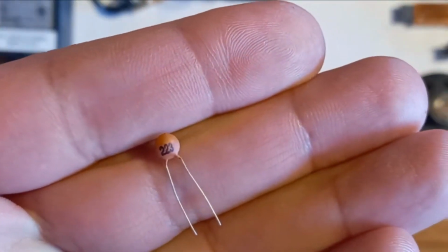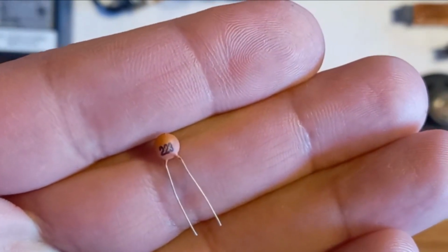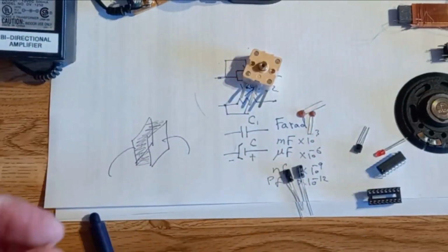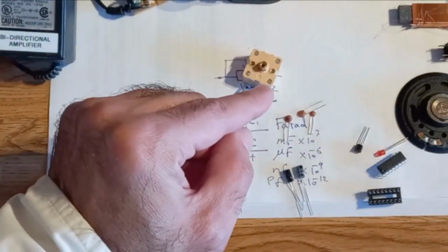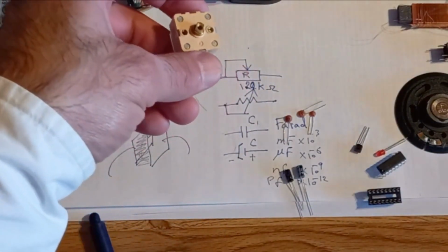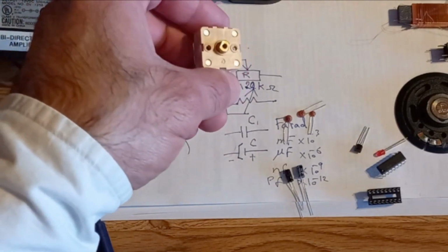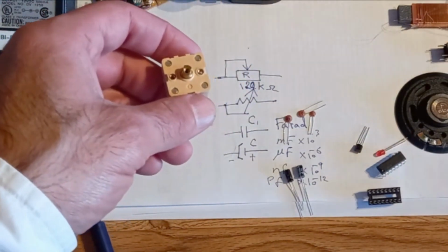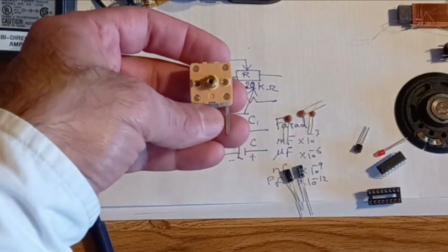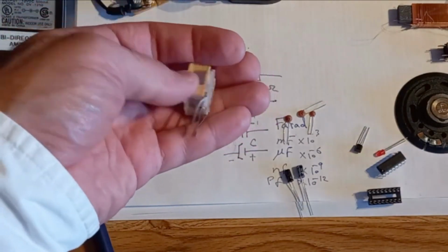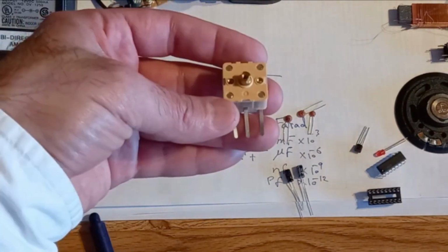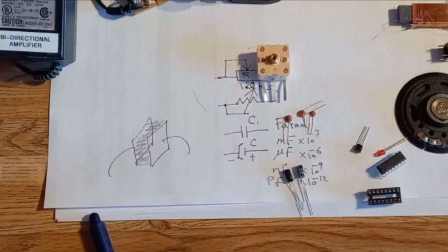Same as this, 3 zeros in front of it, that's 22,000 picofarad. So that's usually in picos, unless it's stated. Other than that, other ceramic, polymer, tantalum, silver mica, all those kinds of capacitors, the value stated on them is actually in picofarad. Variable capacitors also, the value is stated on them.